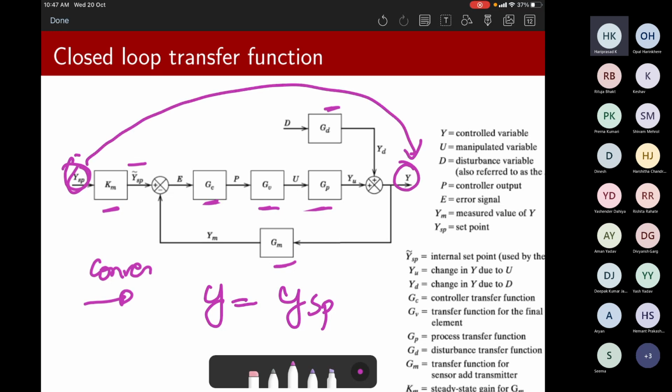To achieve that, you have now added up n components inside. If it would have been one controller, it is okay, because the controller cannot work alone. It would bring in a big handicap. To aid the controller, you put a sensor. To operate the controller signal, you put a valve. And to feed the controller, you put a comparator where you do another transformation.